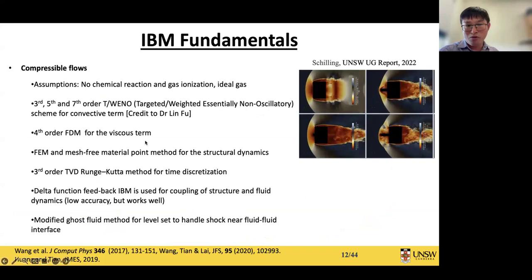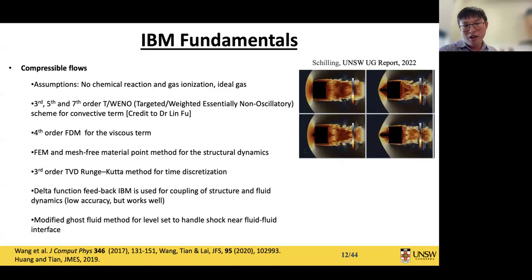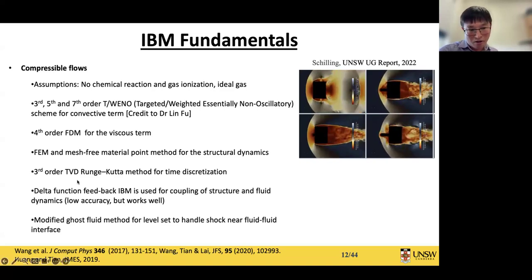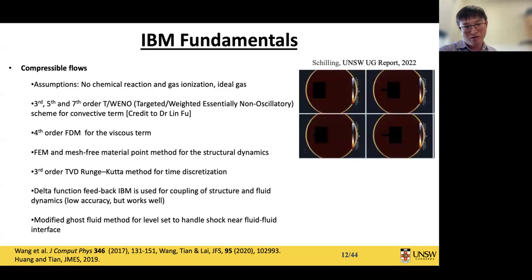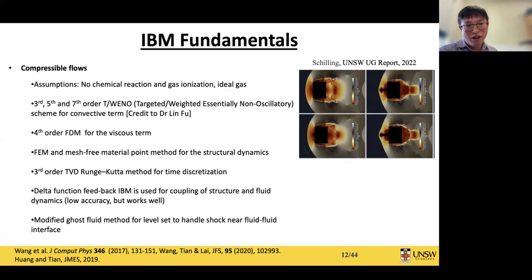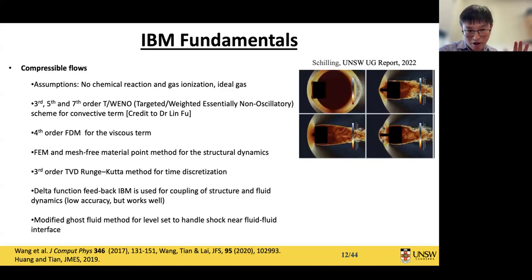And for structure part, we can use mesh-free method, material point method for the structure, or FEM for the structure solver. Okay, and we use 3D TVD Runge-Kutta method for time discretization, and similarly we use delta function here to implement the immersed boundary method, and we introduce modified ghost fluid method for level set to handle the shock near the fluid structure interface.